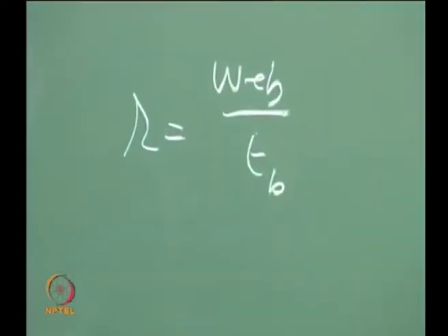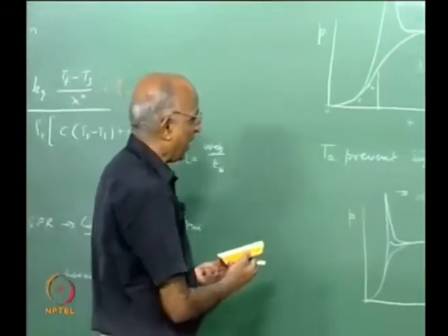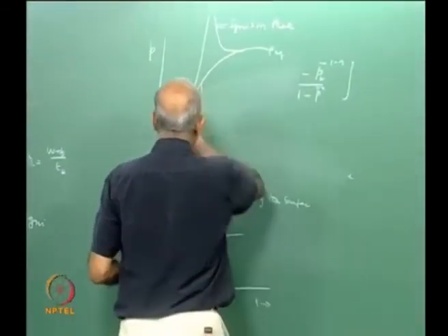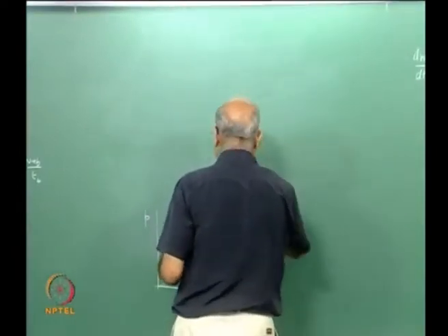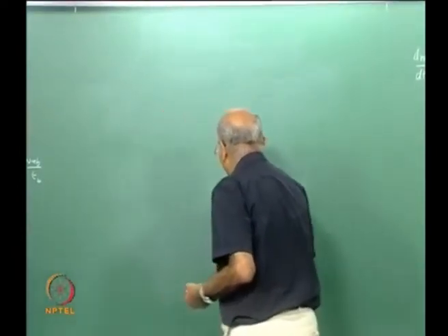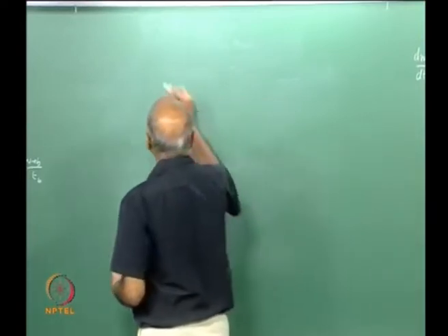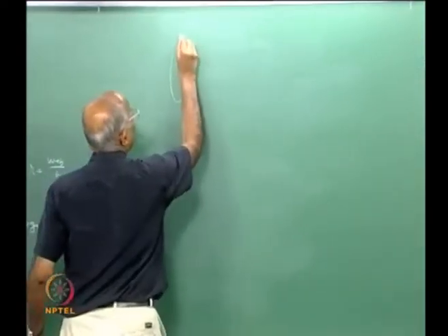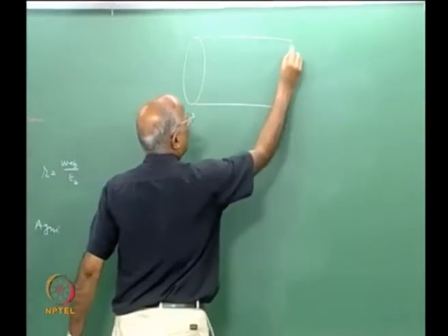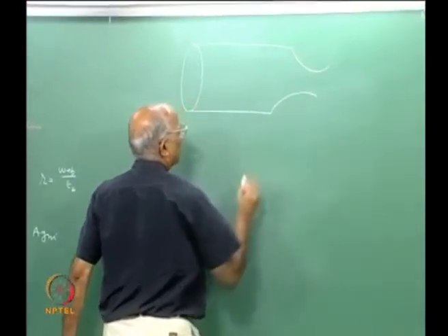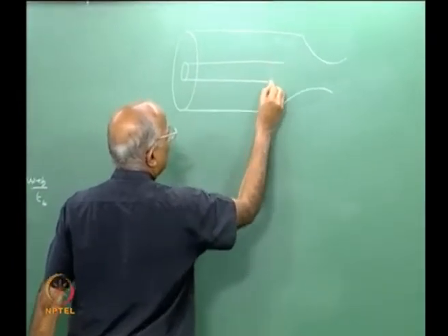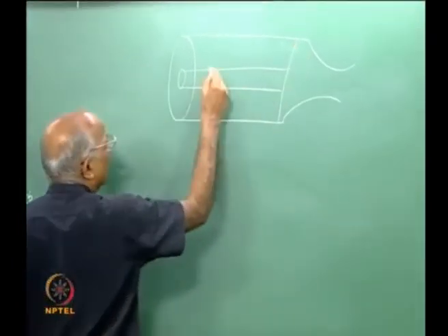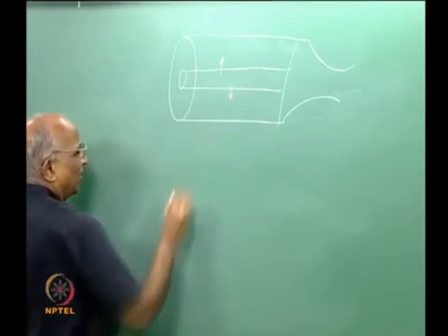But now the problem is still worse. Let us consider two cases. We said the solid propellant rocket of the Space Shuttle is a very large motor, diameter around 3.8 meters, length around 40 meters. Let us say it is also some star shape, but we just say a simple radial burning outside.